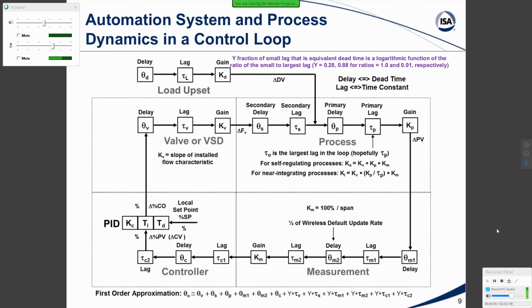Now, what's interesting in the literature, and I think particularly for internal model control, is that they showed the disturbance on the output of the process, not the input of the process. And so it bypassed this primary lag. They didn't see the advantage of the primary lag in slowing down disturbances. And Shinsky really took a big objection to this. It's one of the sources of disagreement out there, and that's what I was trying to resolve by going to the near integrating approach and tuning rules to make them come together.